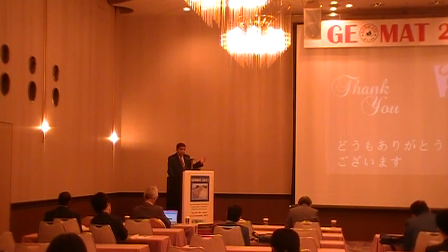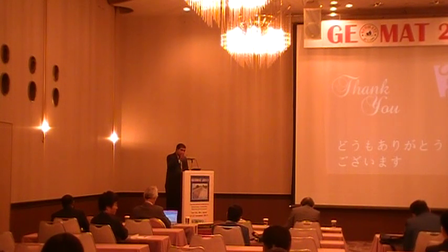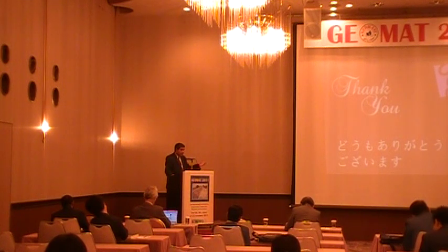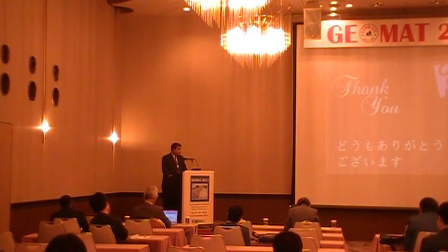The effect of hysteresis of drying and wetting might influence the suction value, but still, as I was showing you, even in low suction values, in sand, if you are able to retain 2 kPa, and in clays if you are able to retain 50 kPa, and in most cases, for example in your country, in Kenya and Sudan, where the soils are typically in a state of unsaturated condition, the suctions are going to be very high. Even though the suctions are going to be more than 1000 kPa, you can take the worst case scenario of 100 kPa and try to design piles or shallow foundations. Okay?